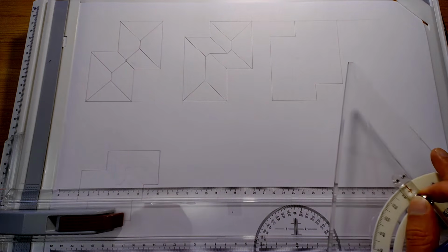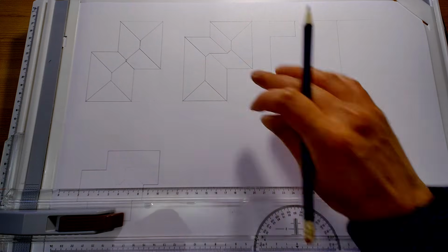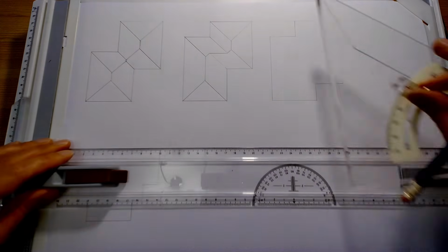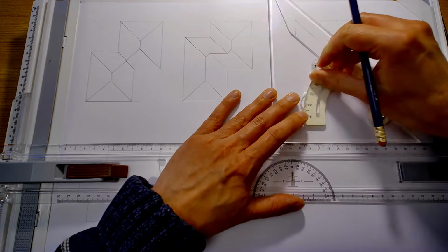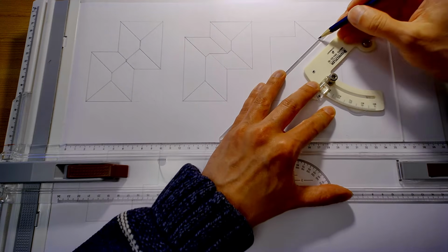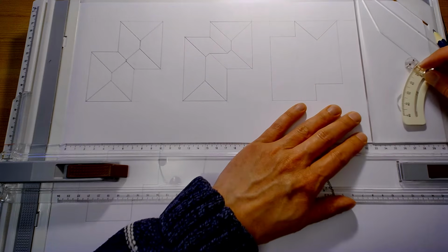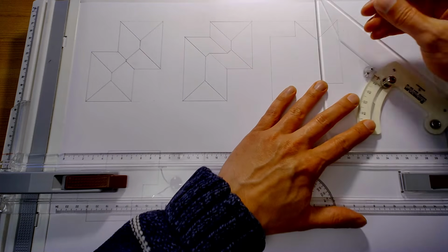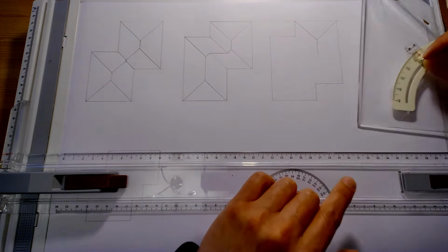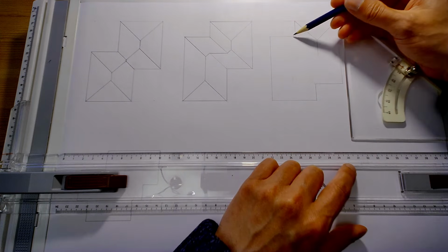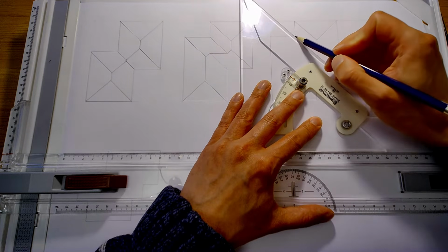Now let's extend the building this way as well and just see how it does alter the shape of the roof a little bit more. Now, what we've got here, we'll start running our ridge along here, but what we see now is that it actually reaches the valley here before it reaches that hip. So therefore we connect it at that point.